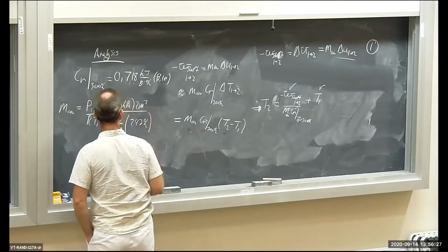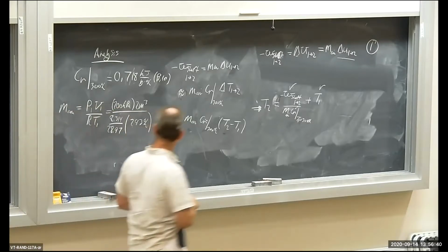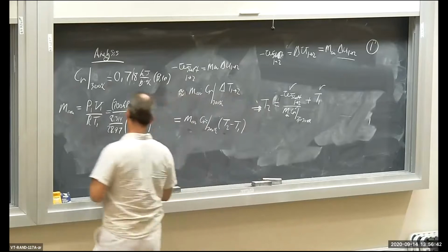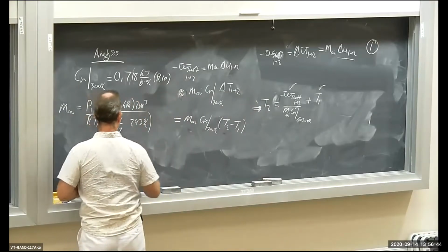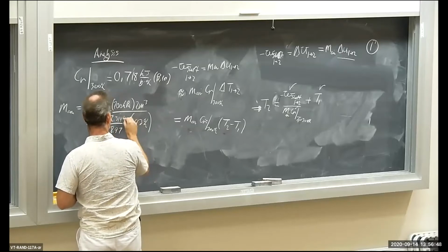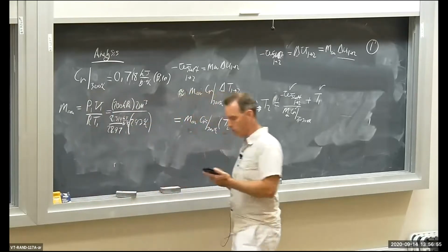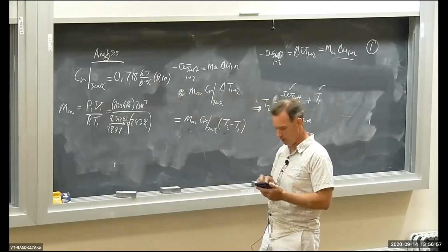Okay? The units here, everything's in kilo. So the kilos will all cancel out, and we should get kilograms for our unit. I'm not going to go through and do the units here. The R will have units of kilojoule per kilogram degree Kelvin. The kilojoule and the kilopascal will cancel out. So we should have kilograms when we do this.